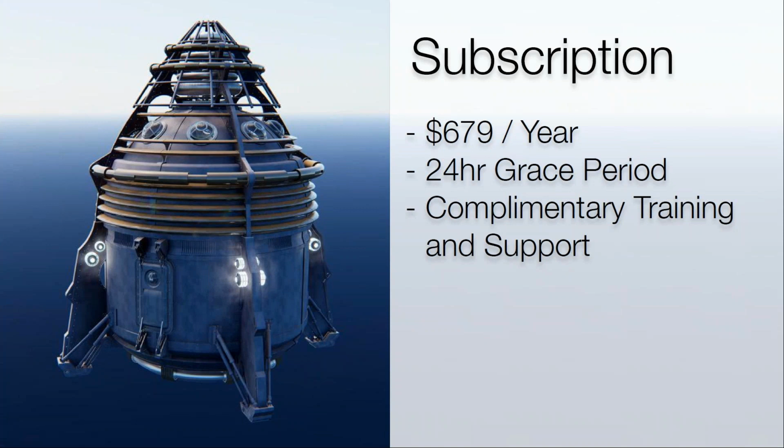What you want to do is while you're in the office, start Enscape. Count to 5, then close Enscape. That checks the license back in, gives everyone back in the office the ability to use all your Enscape floating licenses, but that initiates a 24-hour grace period for you. So you can go off-site, start Revit, start Enscape, and it's fully functional for 24 hours, okay?